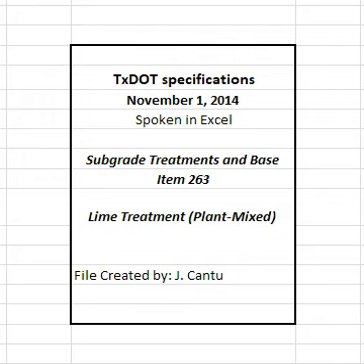6.1.2.2 Thickness deficiency greater than 1.0 inches. Remove and replace areas of treated base found deficient in thickness by more than 1.0 inches, unless otherwise approved. Take exploratory measurements at 50 feet intervals parallel to the center line in each direction from the deficient measurement until a measurement is not deficient by more than 1.0 inches. If, in the judgment of the engineer, the area of deficient thickness should not be reworked, there will be no payment for the area left in place. The minimum limit of non-pay will be 100 feet.